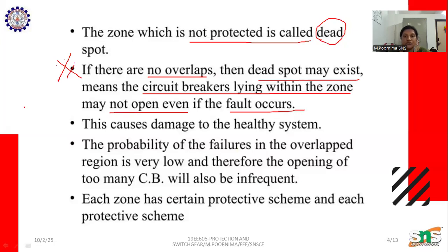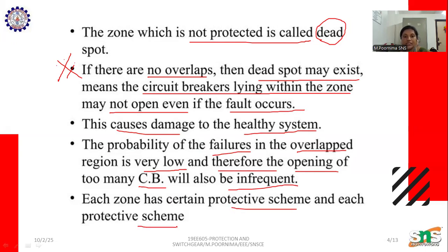Then finally, the fault will not be cleared, and this causes damage to the healthy systems. The probability of failures in the overlapping region is very low. Therefore, the opening of too many circuit breakers will be infrequent. Each zone has a certain protective scheme.